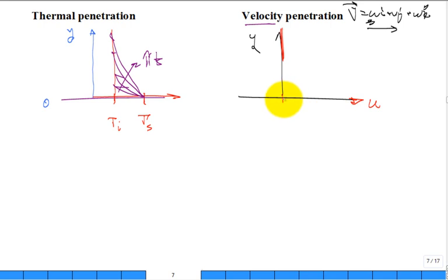And then, just like I abruptly changed the surface temperature, I'll abruptly change the velocity at y equal to 0. We'll make it go all the way out to something like u naught, boom, or Us. This is an impulsively started plate in a semi-infinite fluid. The bottom plate was at rest, and now, boom, it's moving at constant speed, u naught, to the right. And guess what you get? A velocity profile that penetrates into the semi-infinite fluid.